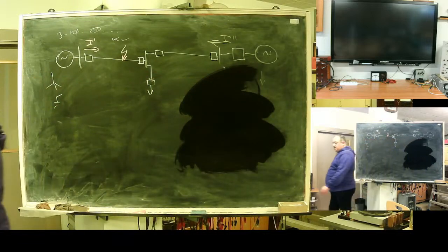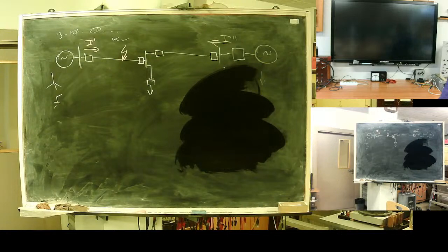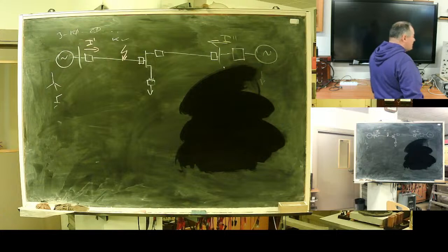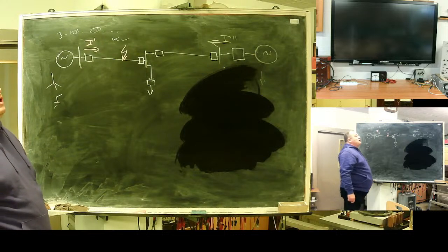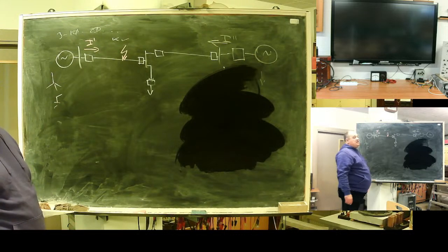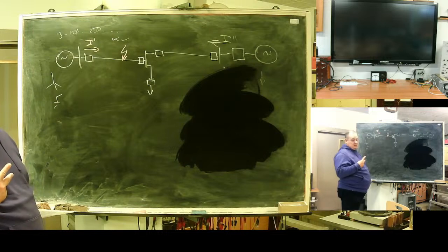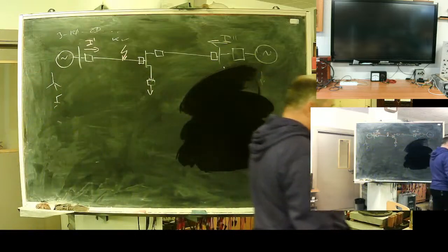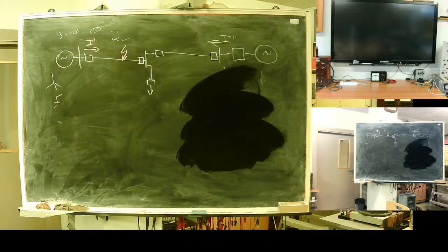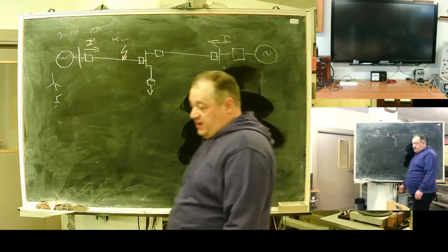Here in Riga, we have some segments where factories were built. And for a factory, one source is not enough. Another thing, large clients like shopping malls need two independent sources, because they need reliable power for fire extinguishing and smoke escape, and so on. At some moment they start pushing the distribution network: can you bring us another source? And at that moment we start to think about the two-side fed network.